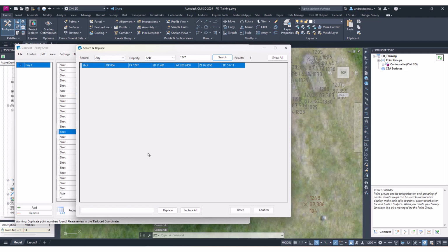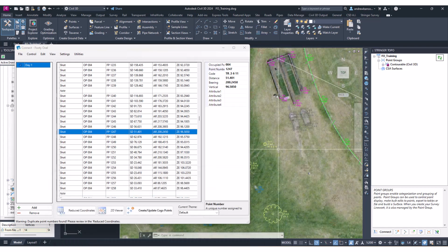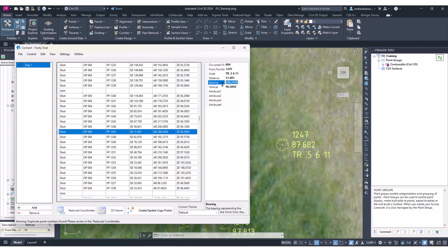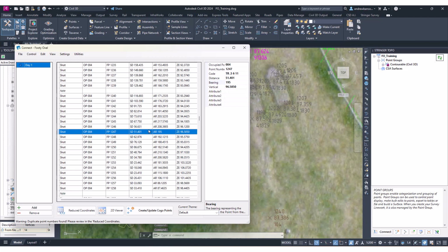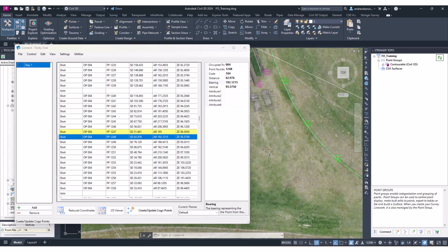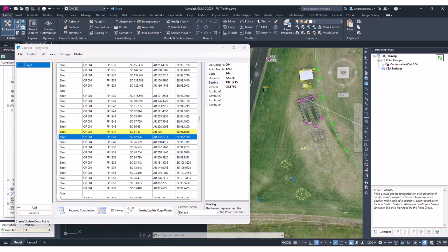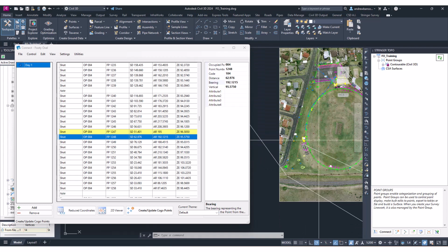And when I click on it, it'll zoom to it in CAD, and it'll also zoom to the raw data entry. Okay. So let's just say, for whatever reason, I want to change the bearing to 195. So hit enter. It's updated the raw data, but the point still exists in the same spot. So we need to go create update, and you can see it shift. Okay, so that entry is now yellow because we've edited that point, but we can see it adjust. So this is really to demonstrate that you have a live connection between your raw data and the Civil 3D points that exist in CAD.